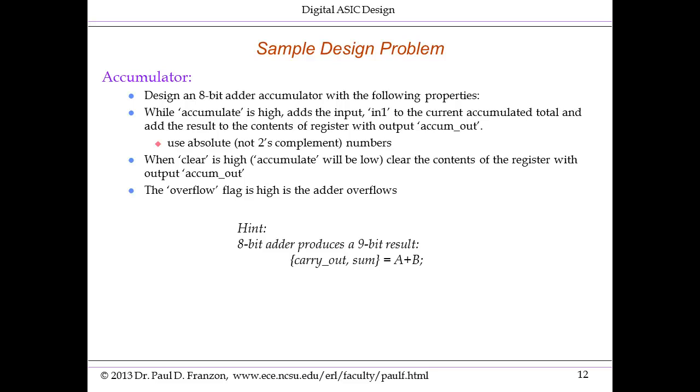Well, I'll remind you that an 8-bit adder actually produces a 9-bit result, the 9th bit being the carry out of the adder, the other 8 bits being the 8-bit sum. In Verilog, this is written as shown on this page, and the details here don't matter, we'll come back to this later, but the point is I'm reminding you that an 8-bit adder produces a 9th bit result, the carry out.